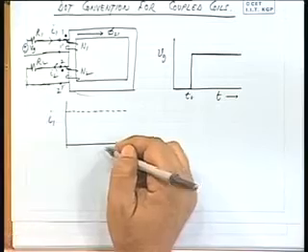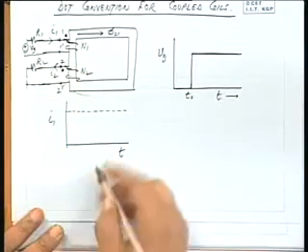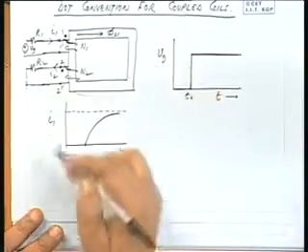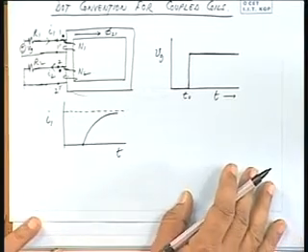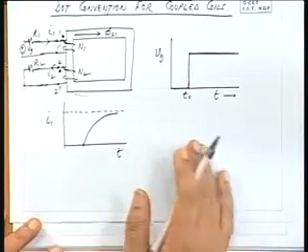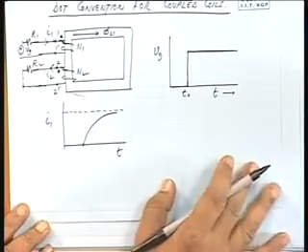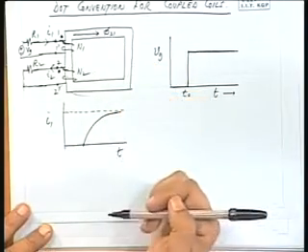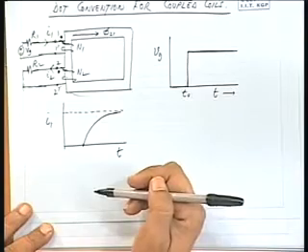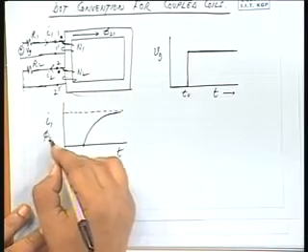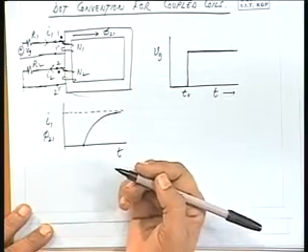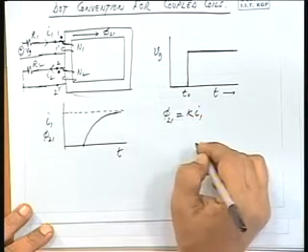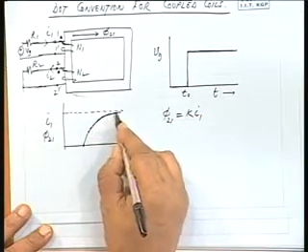Suppose this is kept open, this coil is not there, then at t equal to 0 it will go on like this, just like any inductor RL circuit. Okay. This you have studied in first year class, principles of electrical engineering. You have studied simple RL and RC transients. So it is behaving like this. What will be the nature of variation of the flux phi 21? It is also identical. It is proportional to the current I1. So it will be like this.